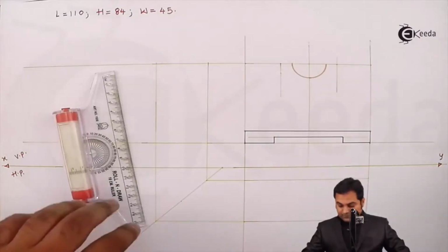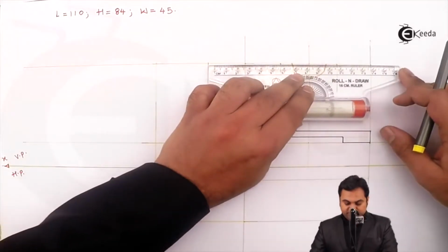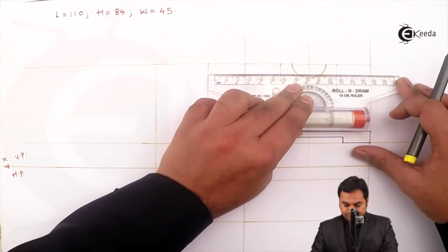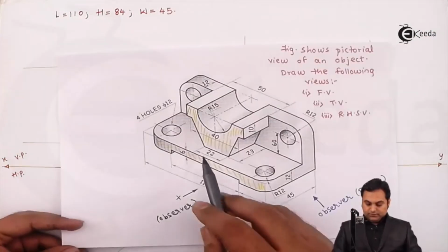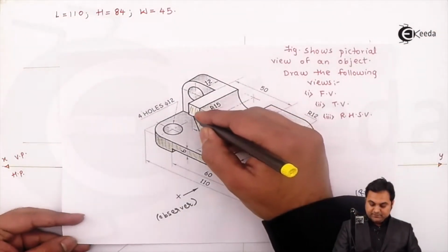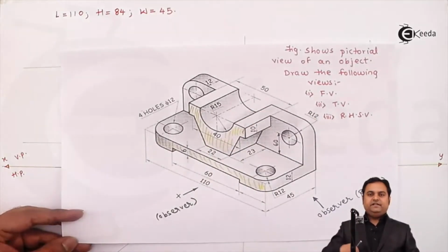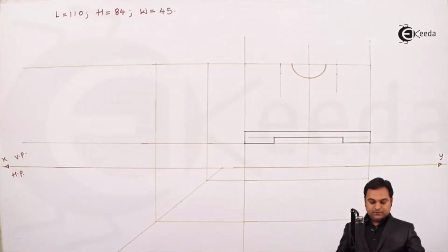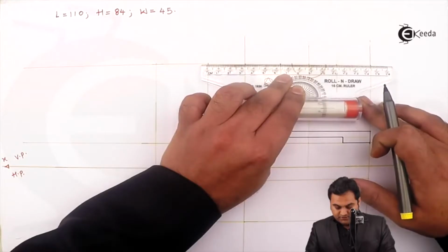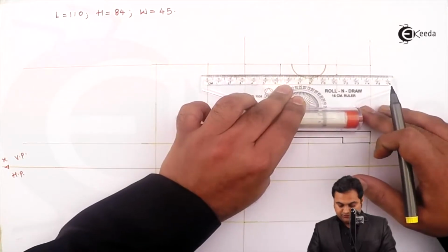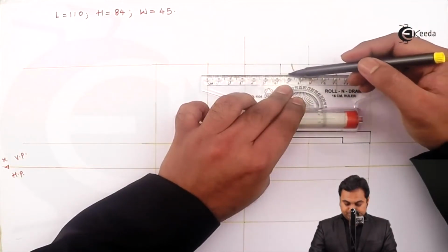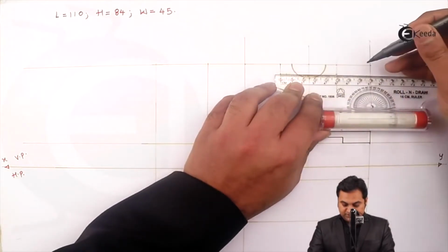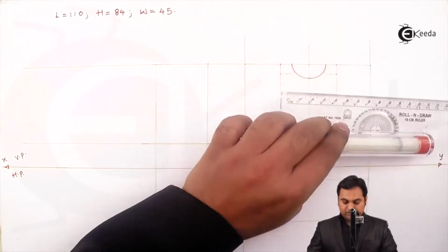So here I have marked 10 mm and transferring this distance onto the other side as well. Here the length is 40 mm. If we see here, after taking the height 10, it goes inside by 5 mm on both sides. For that, here I'll draw a light horizontal line on both sides. 5 mm on one side, 5 mm on the other side.